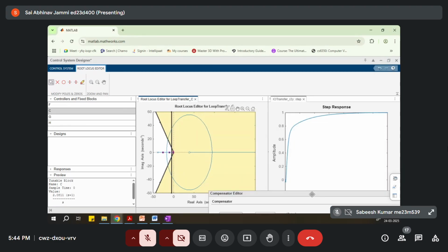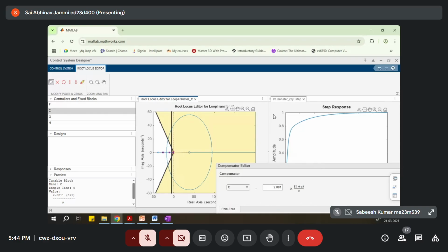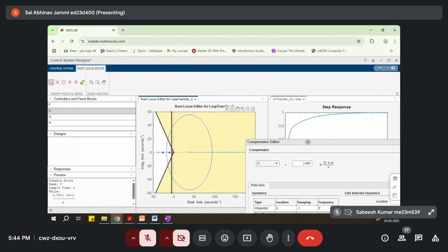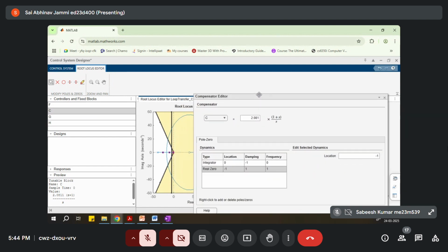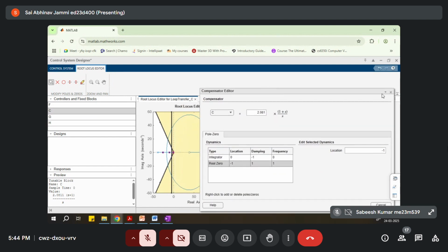It seems to appear good, right? So now I have my poles in the white region. I'll go to my limit, because essentially when my poles are crossing this line, I'm violating my, which constraint? My maximum peak overshoot constraint. So the best optimal solution will be just on the border, right?